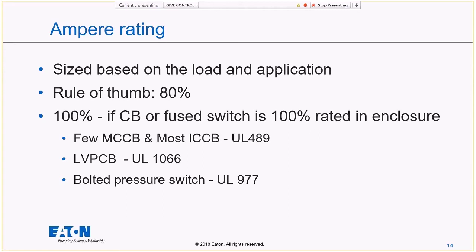I see them used very frequently where space is a major concern, where it was already designed with one space in mind and now it's really hard to change it. Then we start seeing the 100% rated circuit breakers or switches being used.